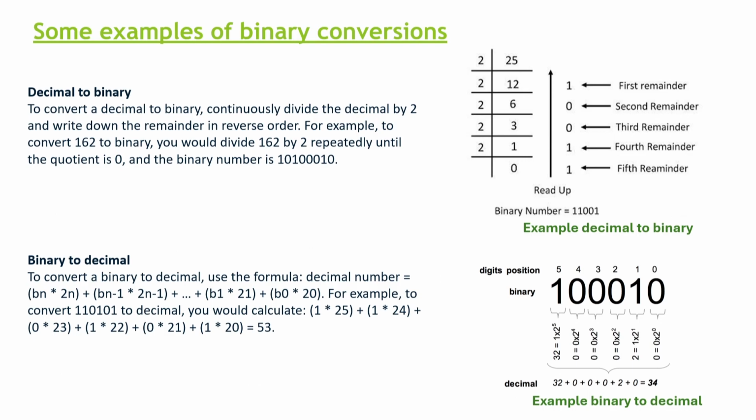These are some examples related to this system. The first important thing is how to do binary conversions in a system. Decimal is the world in which we always live, but for the microcontrollers we have to translate it to the binary world. In order to go from decimal to binary, you need to continuously divide the decimal number by 2 and write down the remainders in reverse order.